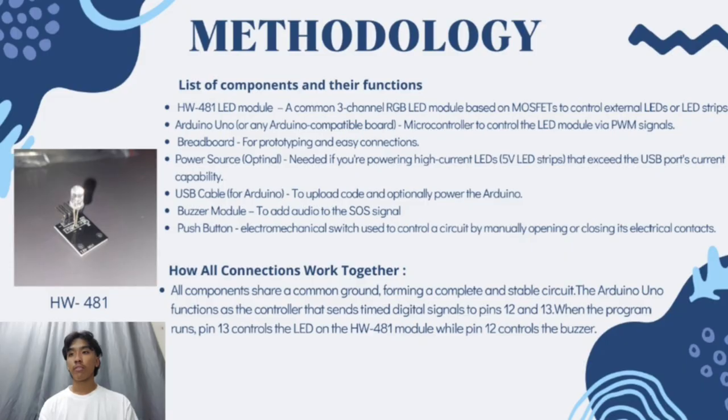Next, the Arduino serves as the main controller that sends signals to the LED and the buzzer. We use a breadboard to make the circuit connections easier, and a power source in case the LEDs require more current than the USB port could provide. A USB cable was used to upload the code and power up the Arduino.